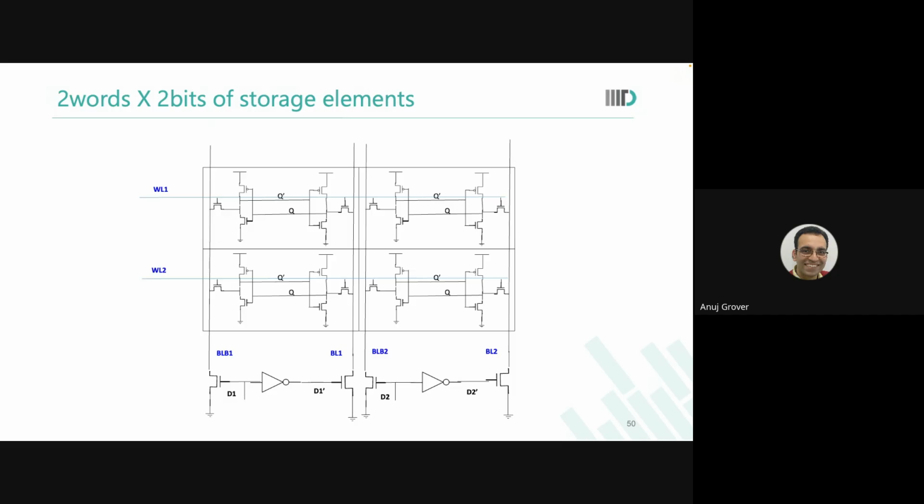Is this clear? So the simplest storage element was the SR latch. We moved to the clocked SR latch, but then we had one data bit to store. So why 2 pins to handle? Why waste area by 2 pins? Just one D pin. So data latch. And then we started to optimize by removing some transistors. We have increased complexity elsewhere. We know this. We've not studied that yet. Those of you who have watched the lecture, you understand where it is. It is in the write operation. But we still gained area.